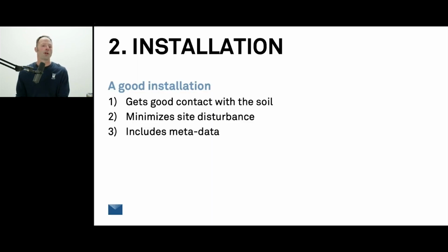Okay, so installation. You might have heard me talk about this before. The installation is going to be one of the biggest places where you can trip up in your data set and collecting good data. And so we're going to spend some time on it here. And I can't stress enough how important a good installation is. And when I think of a good installation, your sensor is going to get good contact with the soil. This is the single most important thing, is making sure that your sensor gets great contact.